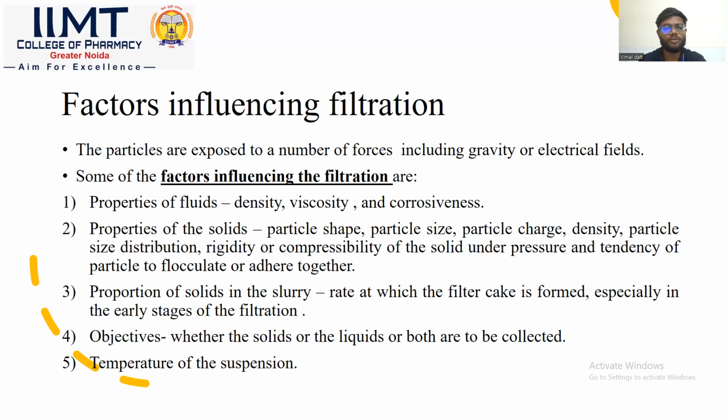Third is proportion of solids in the slurry, rate at which filter cake is formed, especially in the early stages of filtration. Objective: whether the solid or liquids or both are to be collected. Temperature of the suspension. So these are some factors that influence the rate of filtration.